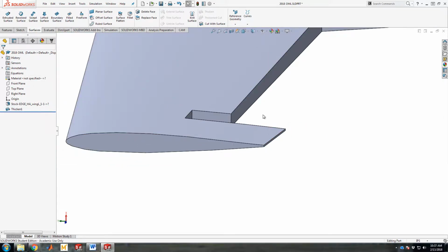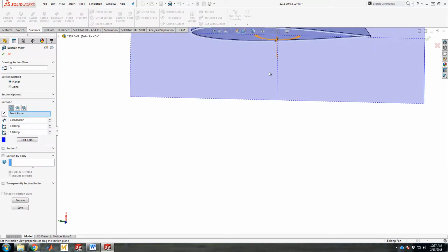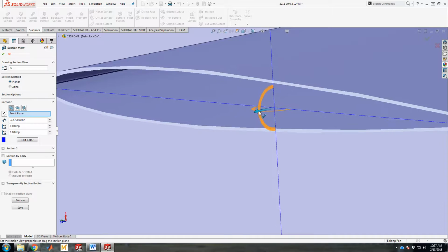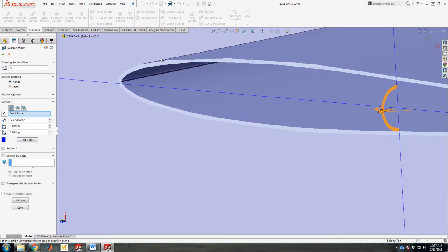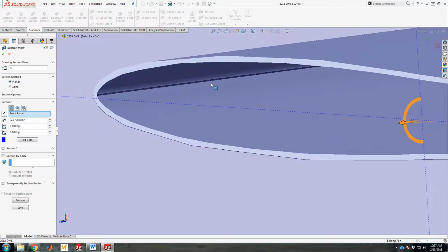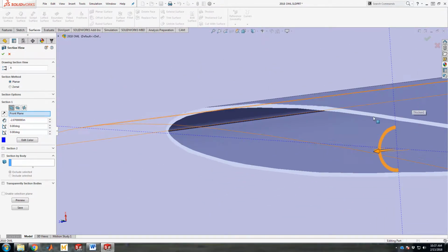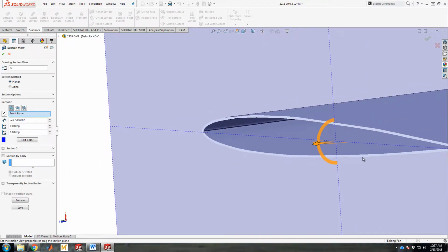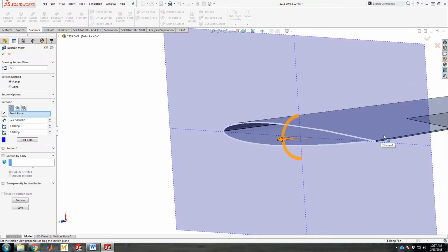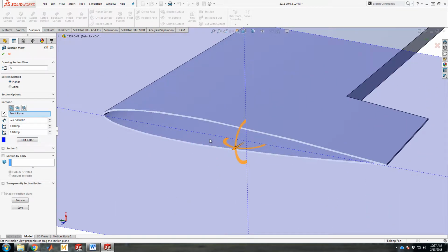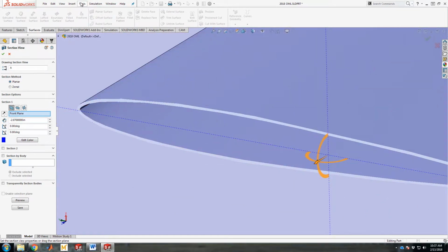We have one solid body now, so if we actually slice this again, you can see there's no longer just a mathematically thin surface. This has thickness. And don't be alarmed by the terrible polygons applied to this. That's just SolidWorks discretization of the truthfully smooth surface it's built. If it put 1,000,000 polys on this model, your graphics card would be so terribly taxed updating it that it wouldn't really work.